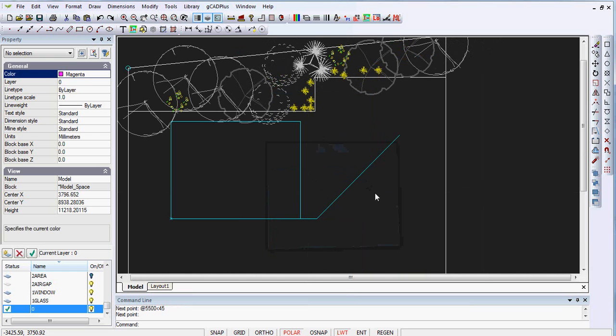Well, suppose on site there was a screening wall running at an angle some distance away from the vegetable plot. You've measured this little distance here, and it's 750. You can determine that on site. And you've measured the length of this. We'll say it's 5,500 or 5.5 metres screening wall. You're not too sure of the angle, but on site it looks to be close to a 45-degree angle. So let's see if we can draw those two lines accurately using this mixture of coordinate systems.